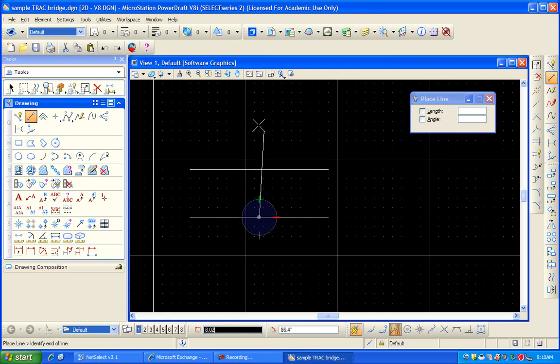But I do want it to be straight up and down, but it's not allowing me. It's allowing me to pick the midpoint there, but up here it's not, and that's because I left the gridlock settings on, which forced all the elements to want to be drawn to these points.